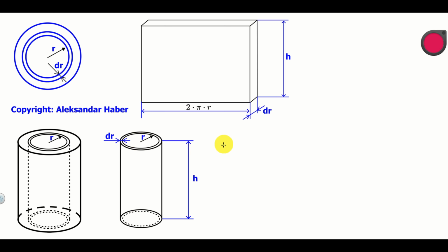The moment of inertia of the shell will be denoted by dI. And dI is equal to r squared multiplying dm. Notice over here that I'm using capital dM, since I used lowercase m for the cuboid at the beginning of this tutorial. Next, let's analyze what is dM. That is, what is the mass of our shell.